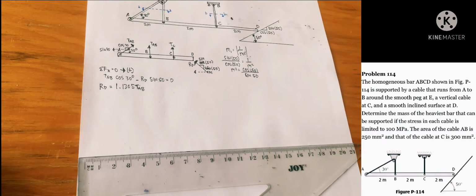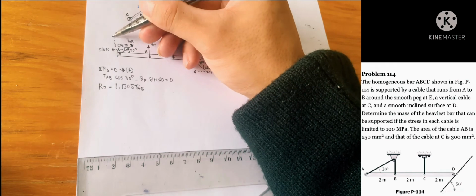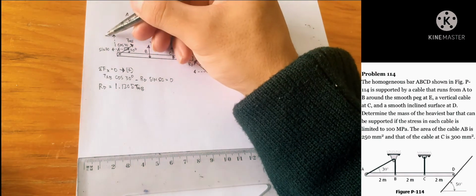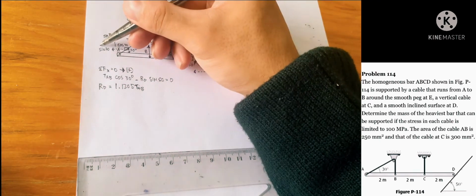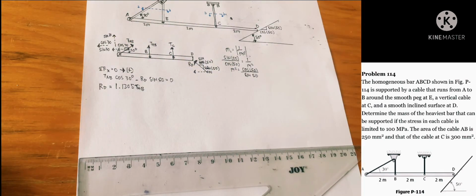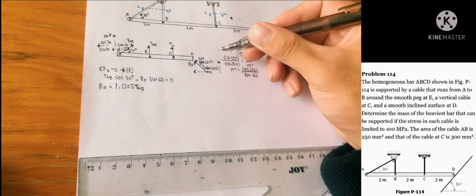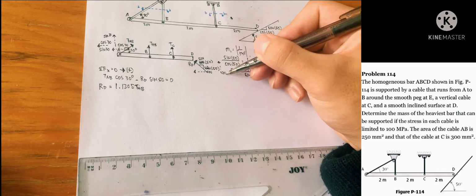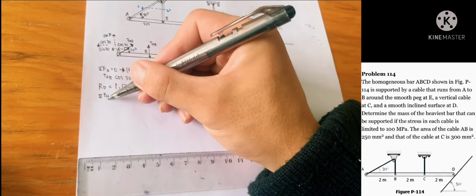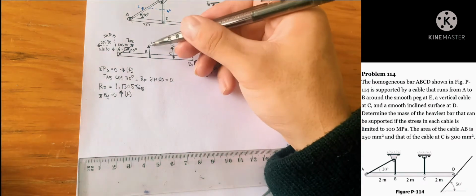So next, we need to summate forces at the vertical. So I will write the components. This should be sine 30, right? It is the opposite since it is with respect to the horizontal axis at joint A, and here at joint D, the resultant at D, or the effect of the 50-degree incline to the joint D, we will write the components.